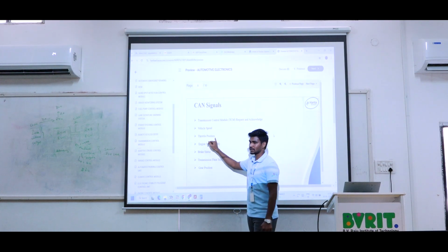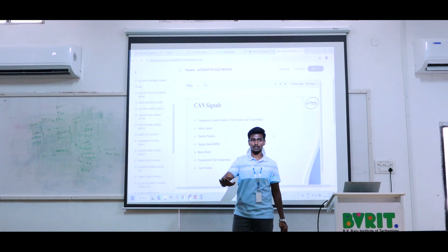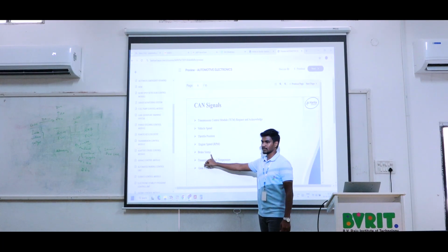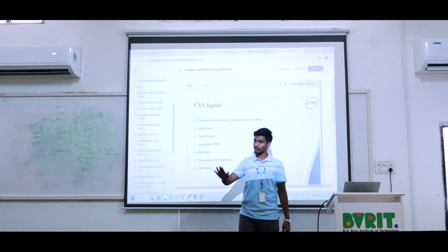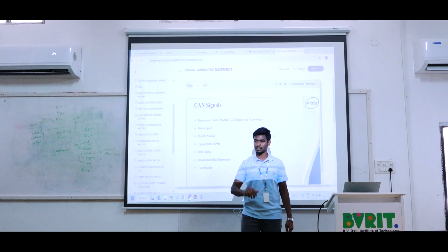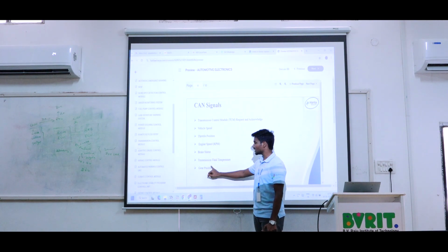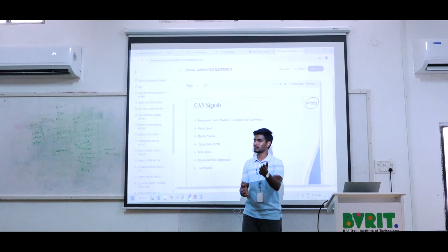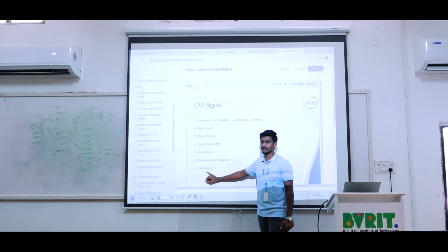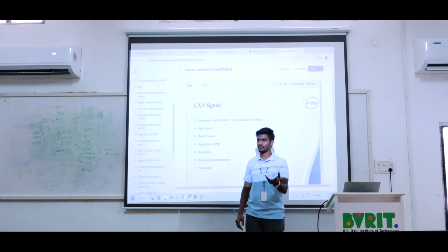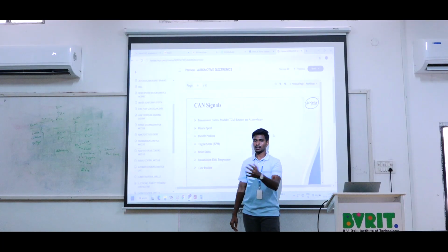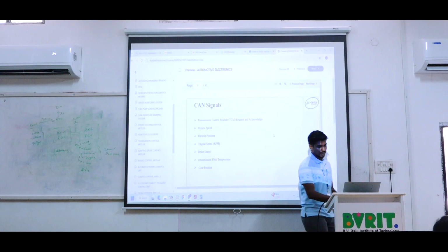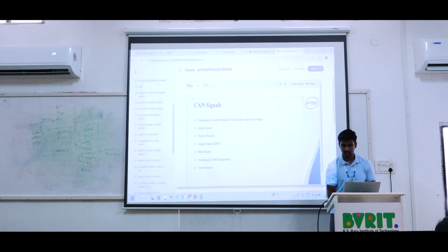Brake status can also be a percentage level of brake applied. Transmission fluid temperature can sometimes have negative values. Gear position covers 5 or 6 gears: gear 1, 2, 3, 4, 5, reverse as 6, and neutral as 7 or 0. Like that you create the signals, and here I will mention that.